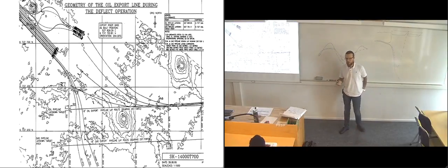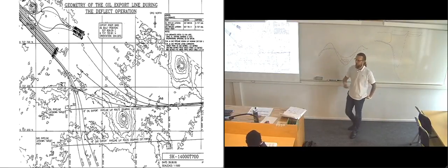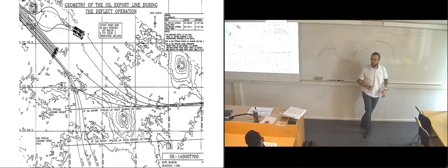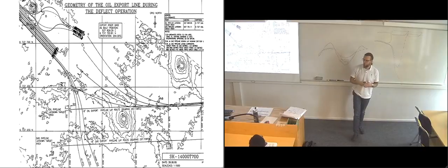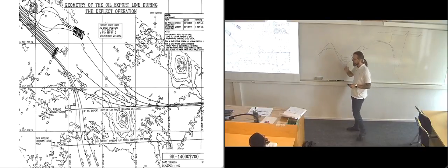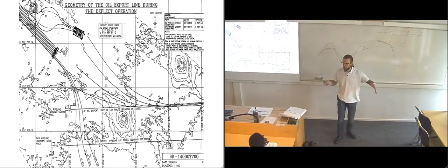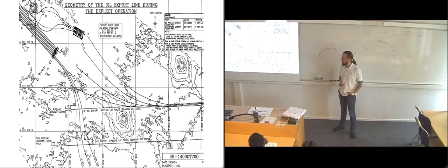If you then have something unexpected happen, if there is a landslide that hits the pipeline and starts moving it, if there is a fishing vessel that drops an anchor and snags the pipeline and starts dragging it, then you will very quickly move from this elastic bending into the plastic one, where you're deforming the pipeline, where it's not going to bend back again. And that's when we have to go in and do replacements of sections in the pipeline. And that's a pretty huge job to do.